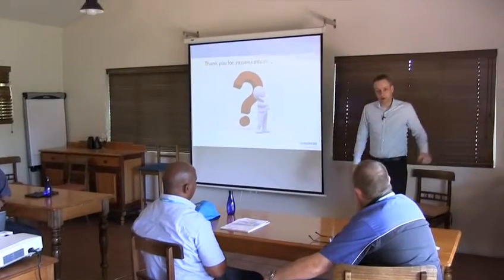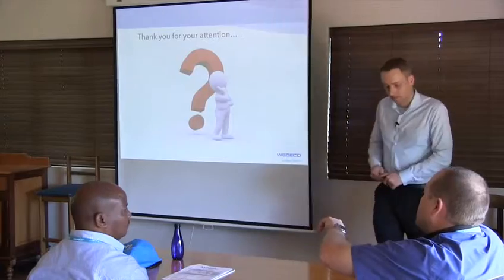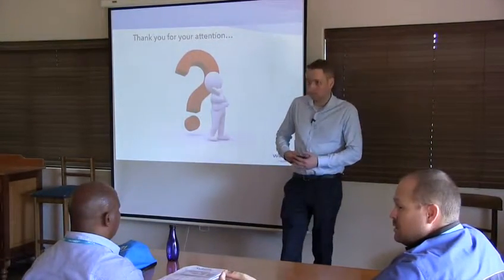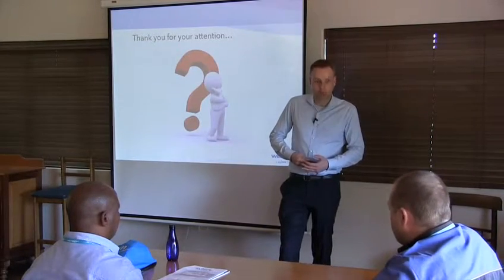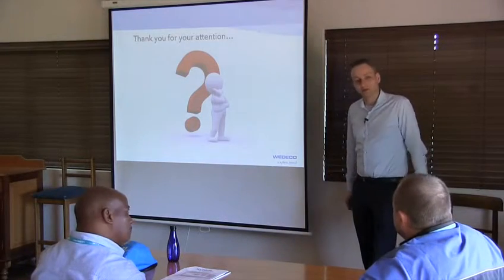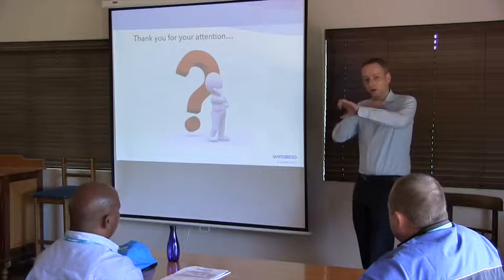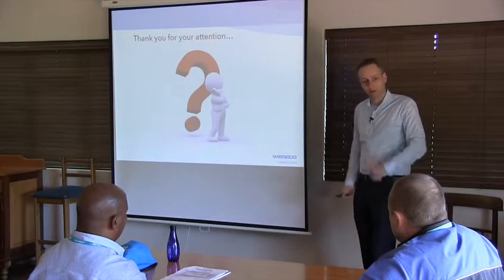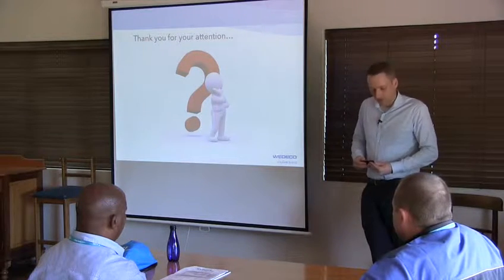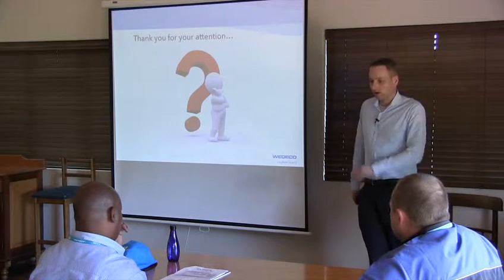And that can cause the formation of byproducts with chlorine in medium pressure UV lights combined with chlorine. Not with our lamps. For our normal systems, even our medium pressure systems, we would just put another quartz sleeve in, which blocks these frequencies that could cause the byproduct. So for the solutions I presented today, it's absolutely safe.